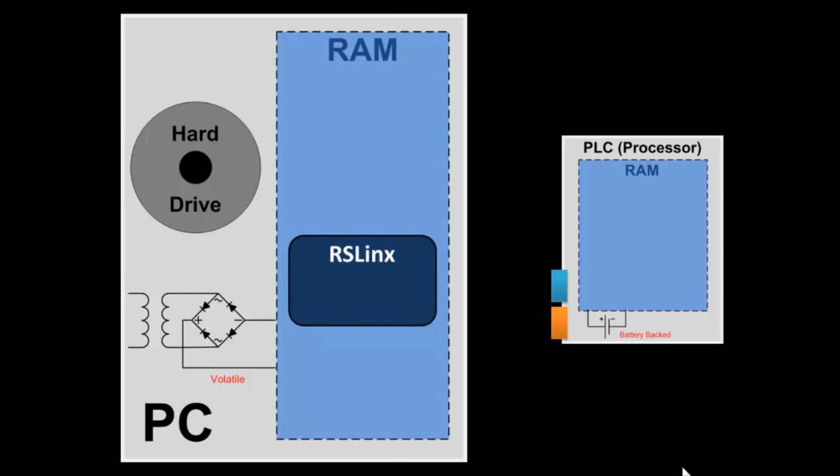The first thing you make note of on your PLC is what serial ports are available on that PLC. Most PLCs have 2 serial ports, probably RS-232 and Ethernet. In the case of Allen Bradley, it's going to have RS-232 and DH485 or DH Plus or Ethernet. Some of the newer processors, it's going to be RS-232 and or Ethernet. Your computer, of course, is going to have more communication ports. Your computer's probably going to have RS-232, Ethernet and USB.